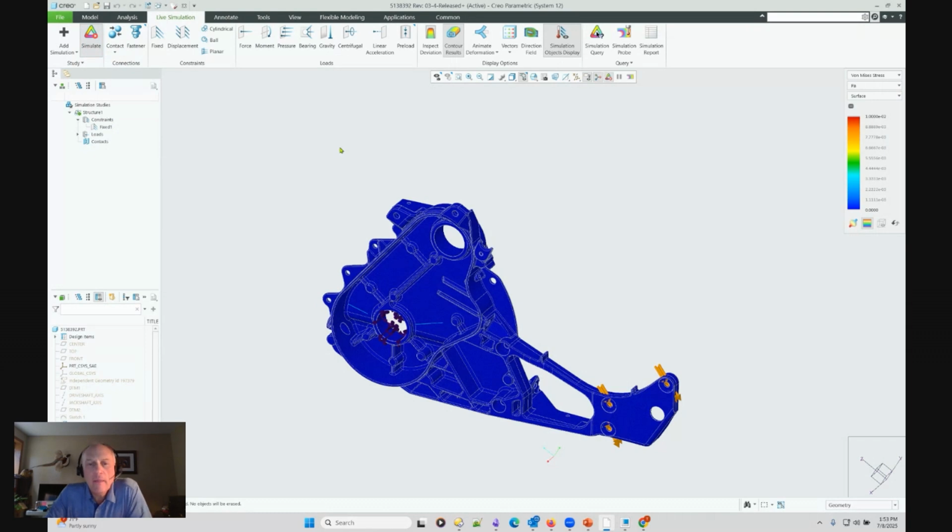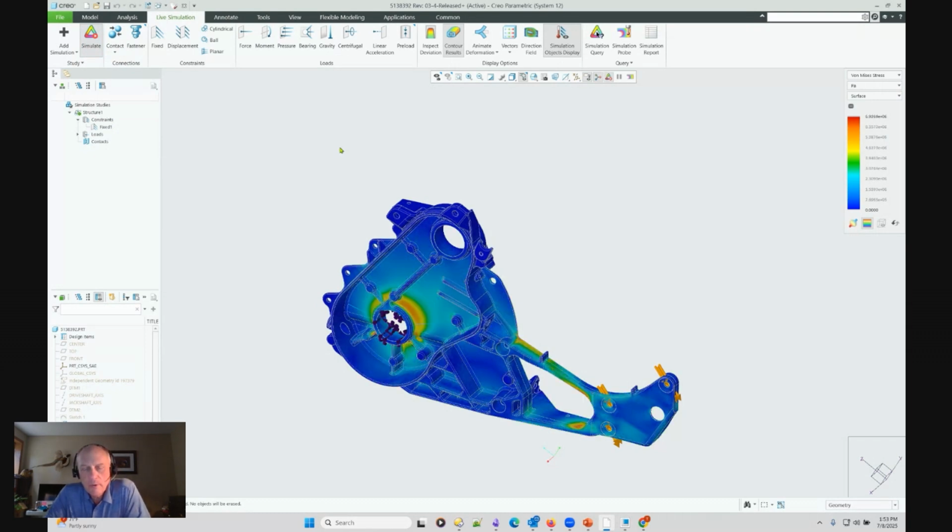And for comparison, this model, you're going to see this run pretty much in real time. So I'll just talk over the top of this. Within about maybe 10 seconds, 15 seconds or so, I get the results on that model. If I was going to run this same model in Creo Simulate, right, it's about a 4.5-minute run on a single pass adaptive with the same load case, same boundary conditions, same geometry, same everything. So you can see the difference between Creo Simulate Live is 10 or 15 seconds maybe, as compared to a 4.5-minute run. And I'm going to get basically the same results, right?